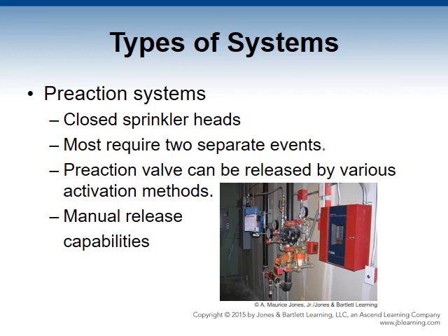Operational arrangement provides progressive higher levels of certainty that there is a fire before the water flows, such as a non-interlocking, which follows the requirements for two separate events to occur. You have a single interlock, which follows the requirements that a detector releases water into the pipe. You have a double, which requires that both the detector and sprinkler head activate before any water flows.